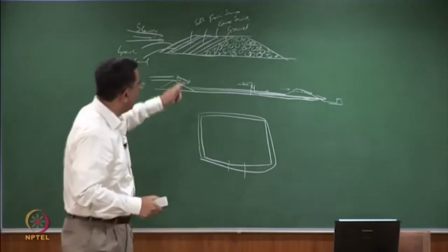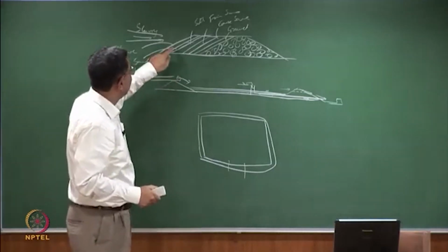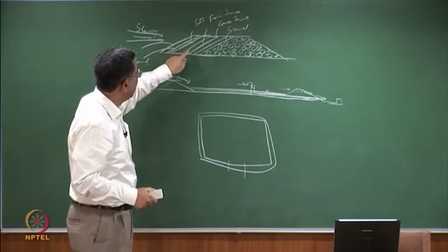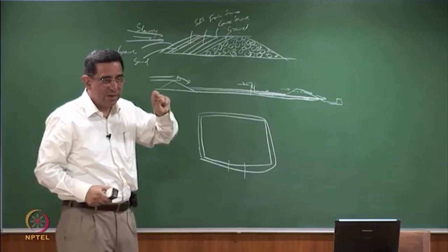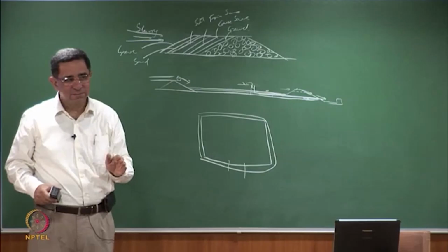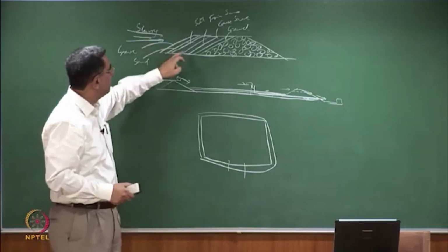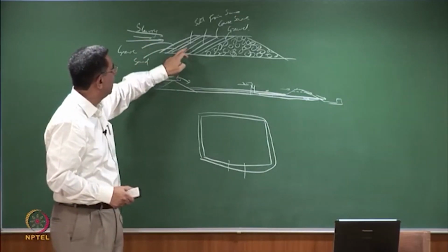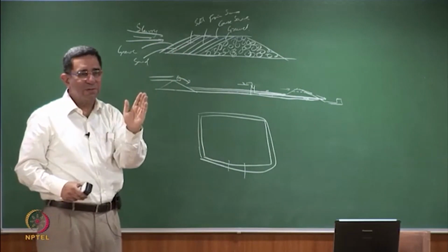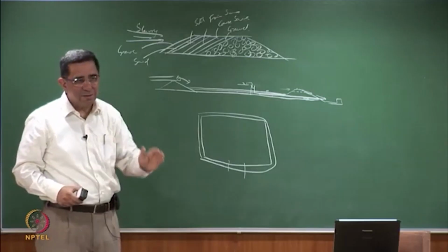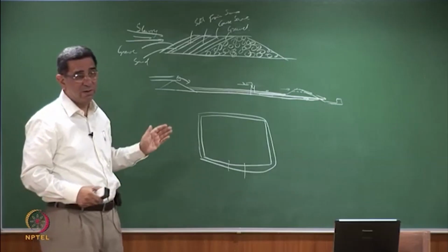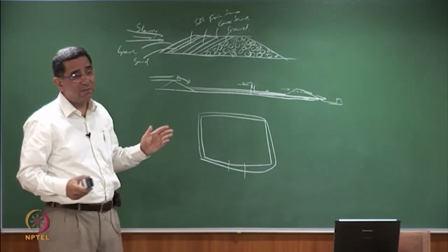Where is my choking occurring here? Is it occurring at this gravel, sand or silt or fine sand? Or what is getting choked? Where are the fines? Where is a layer of fines formed? No. The fine silt comes and is held by the silt here. This silt will allow the water particles to go through, but it will not allow the fine silt part. So the fine silt particles come and form a thin film on the silt. Can I unchoke it? We don't have an arrangement.